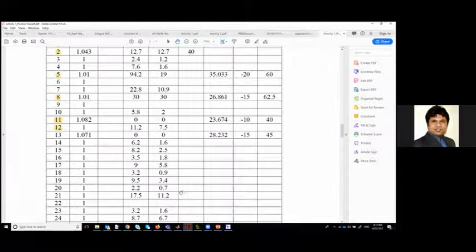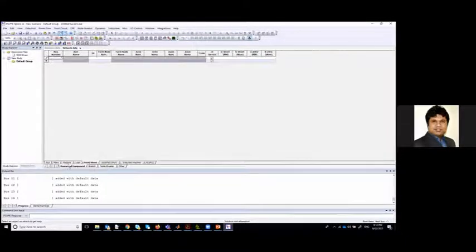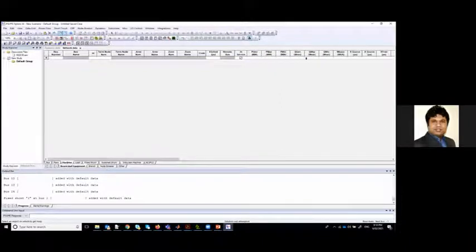We have PG. And if you look, there will be 4 more generator buses. For these, you need to put P. You don't need to put Q actually, okay? For a generator bus, you don't need to put Q. I have mentioned Q just to check your result here. These things you don't need to put. If you go to the synchronous condenser, let's say for the generator, in bus and equipment, if you go to machine, just put the values of Qmax and Qmin for bus 5, 8, 11, and 13. You don't need to put all this information.